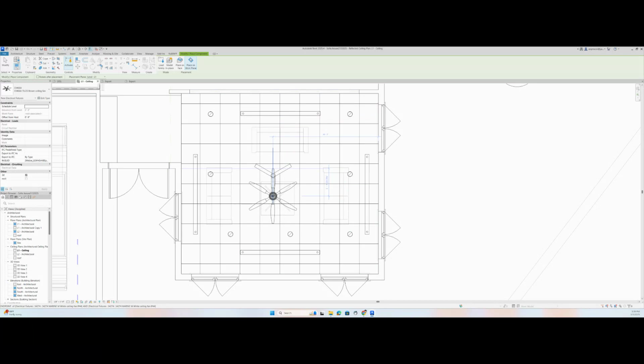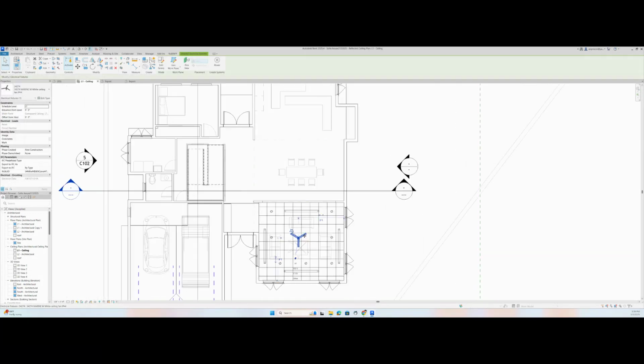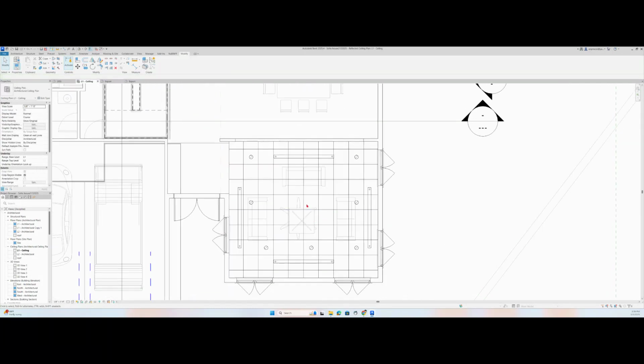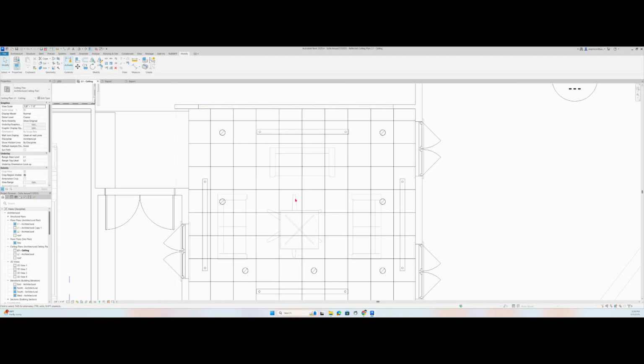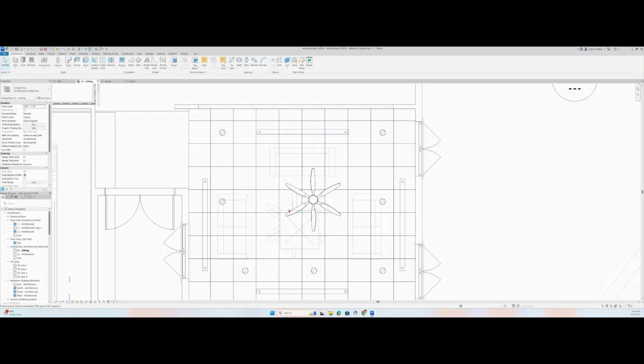And I'm gonna place it kind of here in the middle, and I'm gonna save this for a bedroom, right? Okay, so let me get my, there we go. You see what I was talking about, okay, with my ceiling fan. Let me get the ceiling fan back, and I'm gonna place it around here. Okay, still, it's placing it on the work plane, so don't follow that advice. Place it on face. So place it here, right? And then we're gonna get rid of this ceiling fan, right?